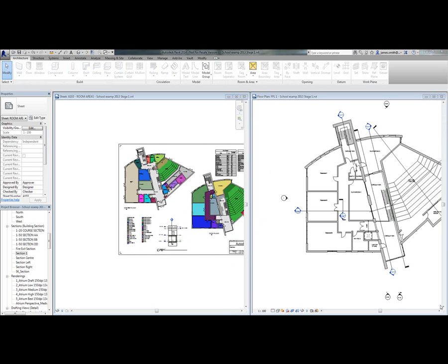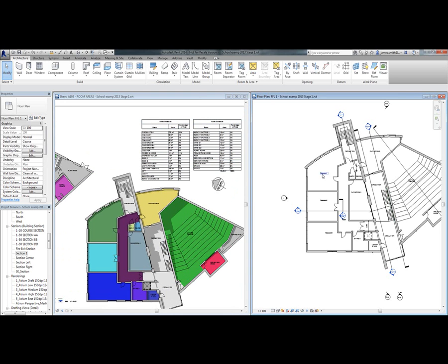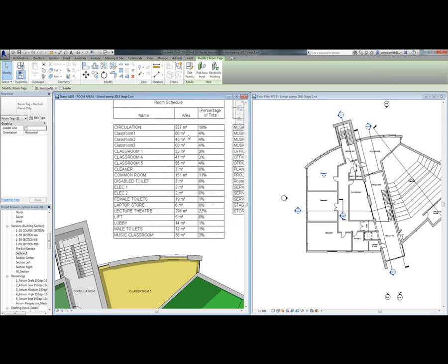We've now looked at how to use Revit to create and manage and add families and data very quickly and easily. I've showed you how to add the doors and the windows and segment the corridors and add functionality and features to them. If we go in now, just to the top, what is very useful, so if I was to go and have a look in Classroom 1 as we've updated, it's also given us the area. So this is all part of the setup. It's created the classroom areas for each one and rounded that off, which is a great feature.